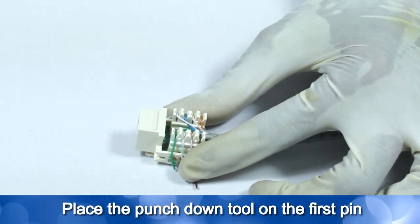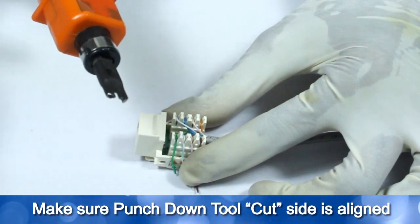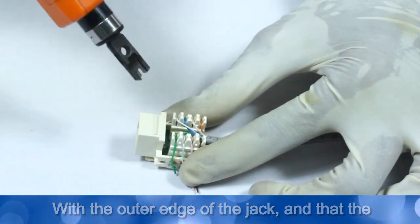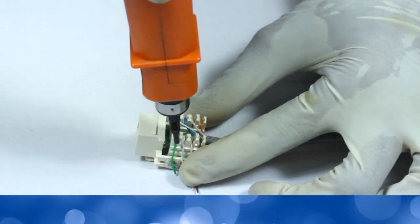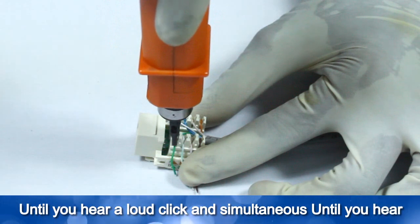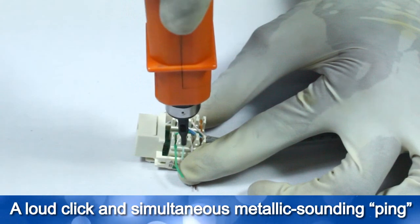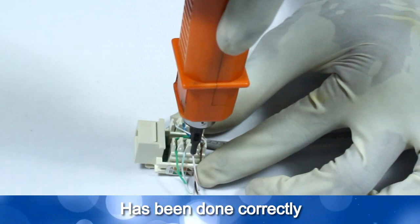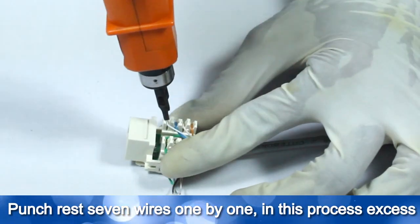Place the punch-down tool on the first pin. Make sure the punch-down tool cut side is aligned with the outer edge of the jack and that the jack assembly is resting on a hard surface. Now press down on the punch-down tool until you hear a loud click and a simultaneous metallic sounding ping. These noises are indicators that the punch down has been done correctly. Punch the rest of the 7 wires one by one.